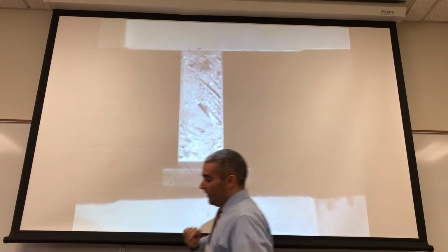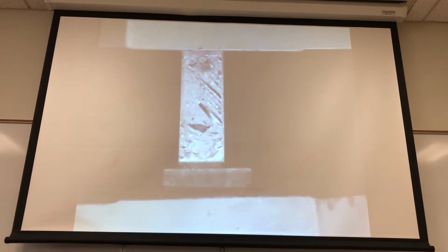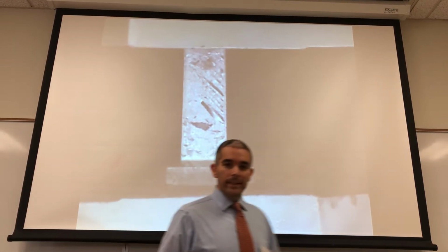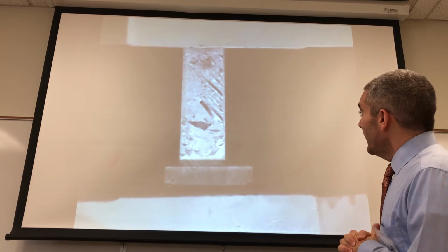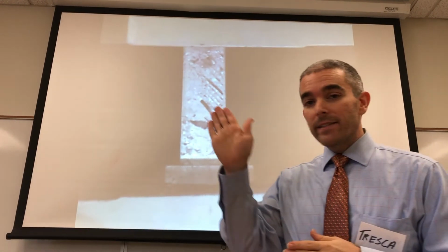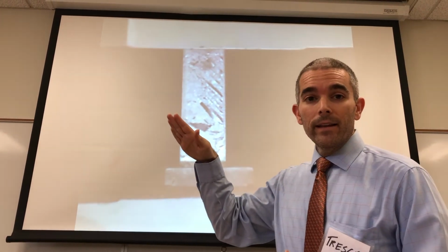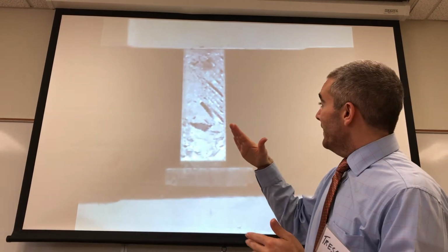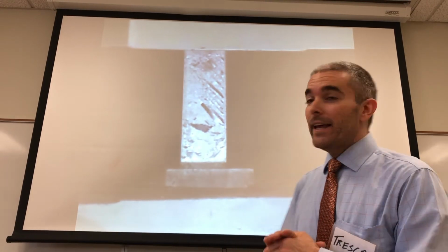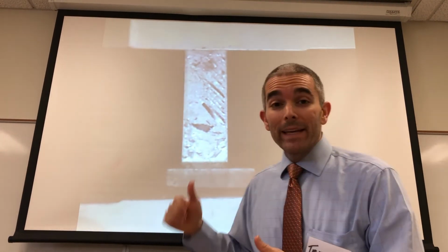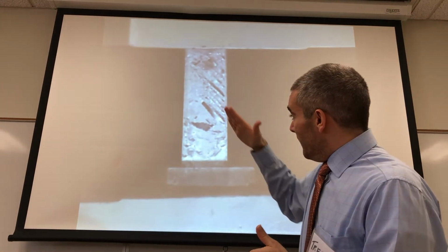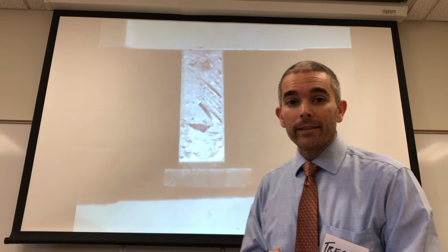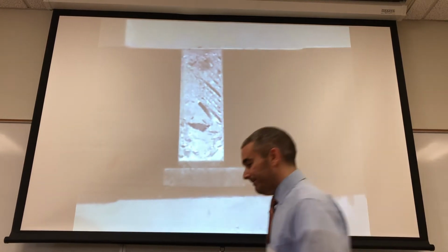I want you to look at those lines, those bands. What direction are those bands in? I think we can clearly see that the bands are on a diagonal. Oh, we could approximate the degrees, maybe. I think it looks close to 45 degrees, something like that. But we can see that it's starting to rip, or failure is starting to have kind of this diagonal path. Let's go ahead and keep loading it.